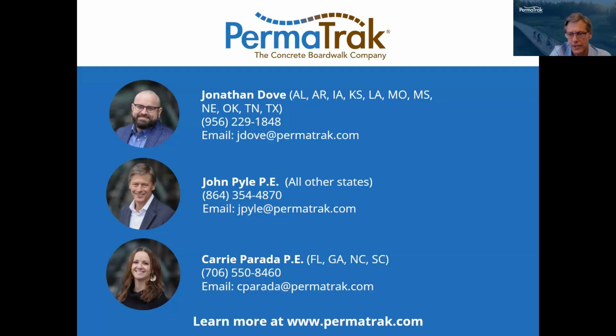There could be boulders or a rock shelf at a fairly shallow depth in the wetland that doesn't allow you to install helical piers. In that case, you do have to consider partial top down, where you get a permit to allow temporary construction impacts, working off of mats to install whatever foundation you need. Then you can come back and install the boardwalk from the top. Again, you're limiting your impacts. You're not having to clear an entire pathway parallel to the boardwalk. So it does help, but there are some challenges associated with it.